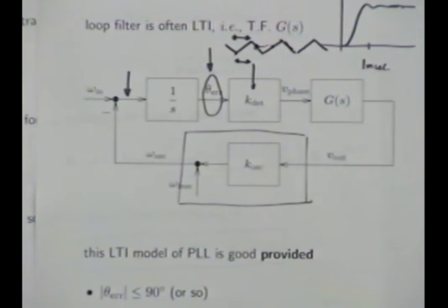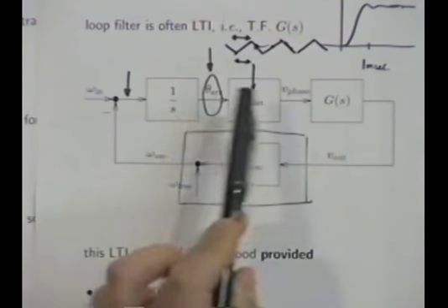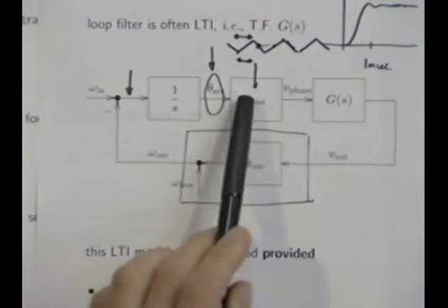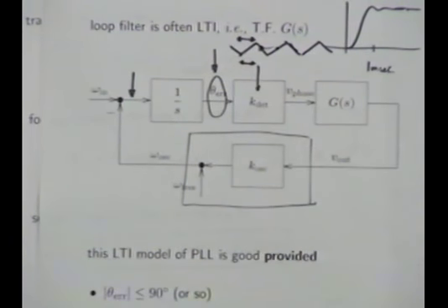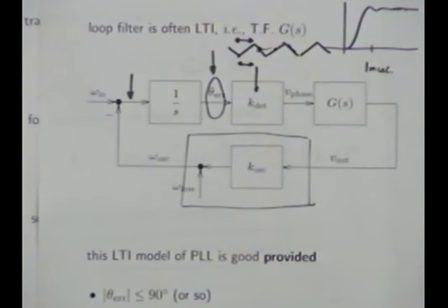That the best way to do it is just sit down, write out all the equations, and some things will be common. Like, for example, the loop gain for sure is this times this times this times that, right? But you'd have to write it all out. And in fact, people can do sneaky things. Like there might be a minus sign here, in which case the loop gain would be the negative of that. And so your best bet is just to analyze the block diagram as if you've never heard of feedback before.